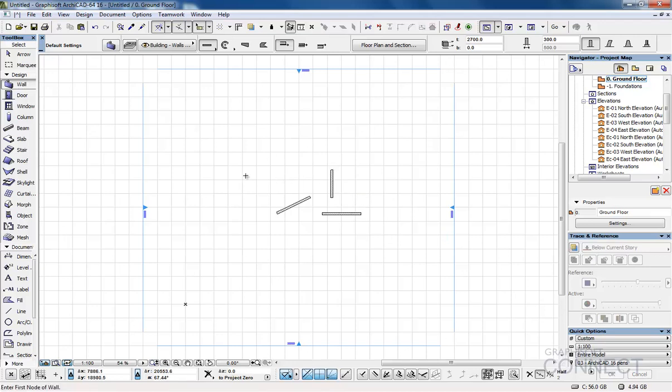If I now want to introduce some different angles, so I'm not snapping to one of these guidelines, I can start again, and this time I'll choose, again, 4 meters, but this time I want to put in the angle. There are various different ways you can do this, depending on what page of the reference guide you happen to look at, but personally I find the easiest way to move between distance and angle or any other fields is just the up and down arrow on the keyboard. So all I do is press the down arrow and type in, let's go 35 degrees. So we just type a size, press enter, and that drops that in.